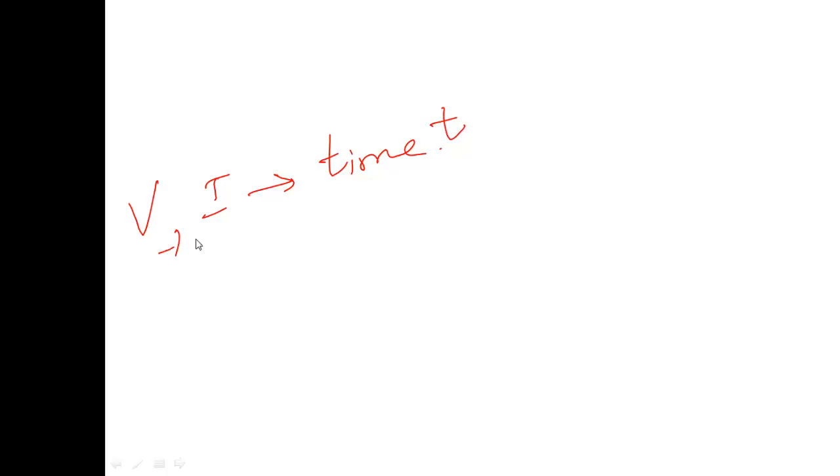And this idea is helping you to go for identifying how the particular limb, the edge of your circuit is working. The edge is, what I mean is the component what you have between two terminals, between two nodes naturally. And when I have some billions of transistors in one complete circuit, how am I able to go for identifying the I, the V, and with respect to the time also for various input conditions.